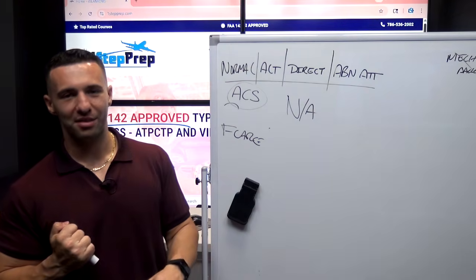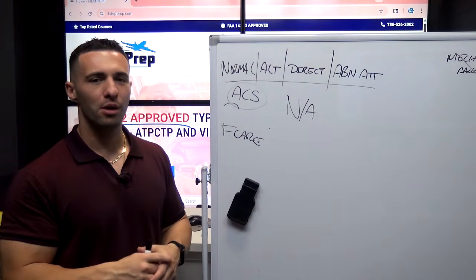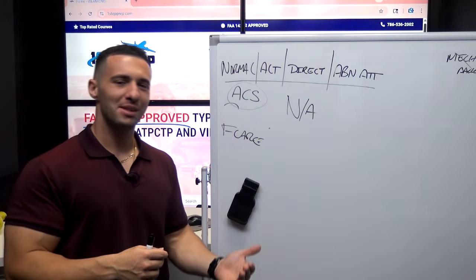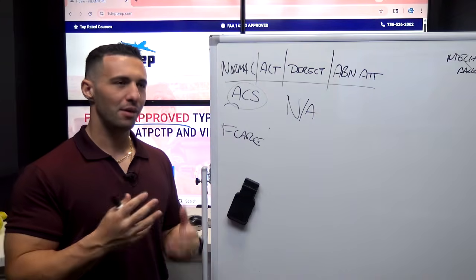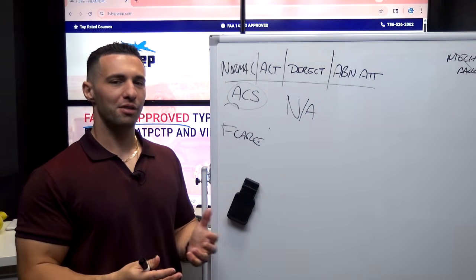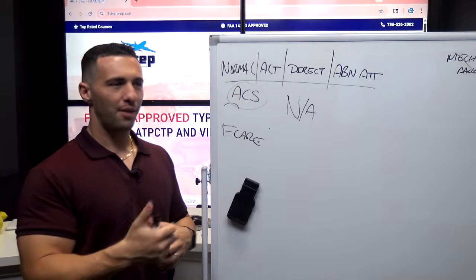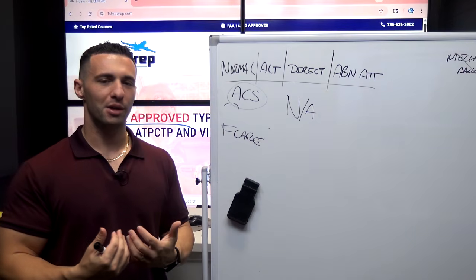You have all of this aft side stick input, so you could quickly over rotate, exceed the flight director bar, which might lead to a speed decay potentially. Like that 50-foot rejected landing, if you're mindful of all these things, it's usually not like a big deal, but it could turn into this thing where you have tons of aft input and then quickly are over controlling and then questioning, why am I over controlling so much?